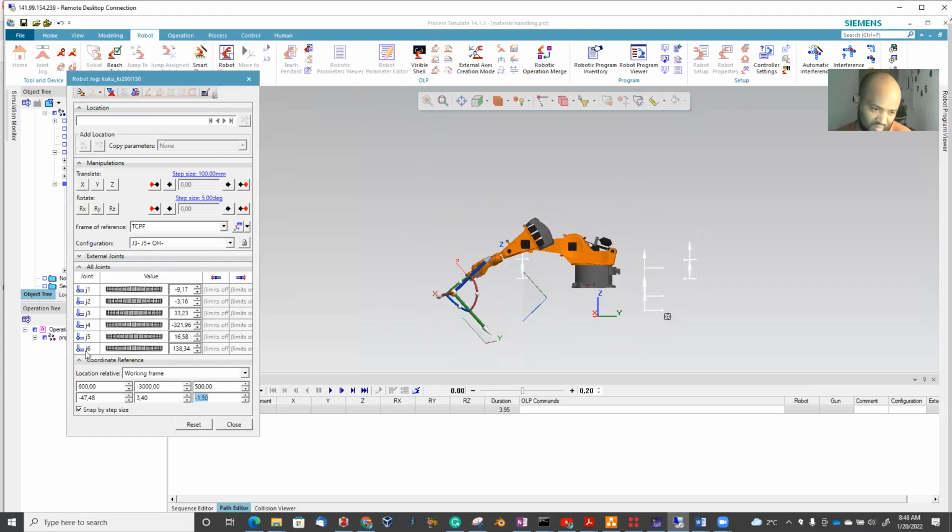So whether you like it or not, between these joint variables and this coordinate frame, there is an inverse kinematics model, mathematics, which translates the information from joint variables to the end-effector position, or to the Cartesian space, or the operational space, and from the operational space into the joint space.